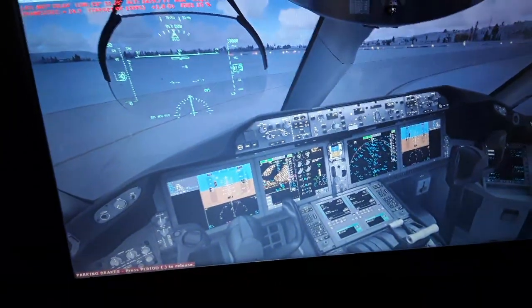We're going to set the runway length, the runway slope, the wind direction and speed, the barometric pressure, the density of the air and the temperature of the air. It's going to give us the takeoff speeds V1, rotate, and V2, like 130, 140 knots or 250 kilometers per hour approximately. We're going to have the takeoff rotation 9 degrees or less,